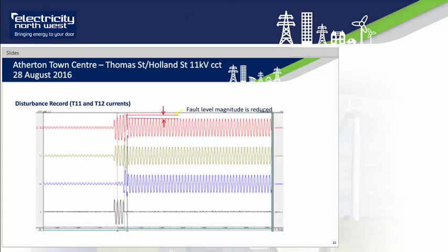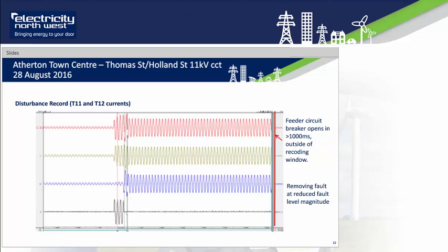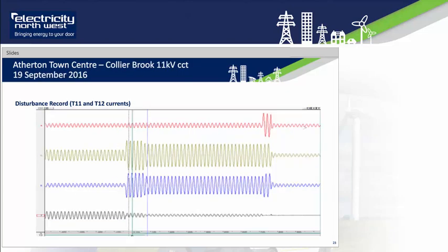Again, we had a fault level magnitude reduction. Unfortunately, the recording was outside of 1,000 milliseconds, so we didn't actually record that. But the feeder circuit breaker did operate, removing the fault again at reduced fault level magnitude. Again, Atherton Town Centre has been busy there.